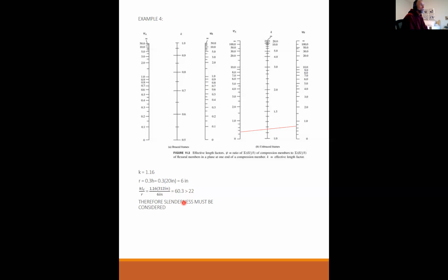But at other points in this procedure, you look at sustained shear versus total shear. And usually shear is coming from some environmental factor that is not sustained, wind or seismic. Neither of those two are sustained. So yeah, you've got to be careful about that factor. Okay, makes sense. Thank you.